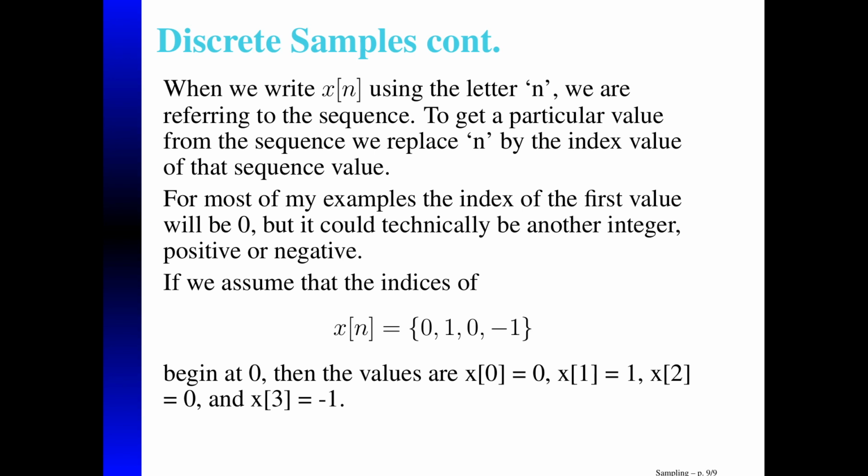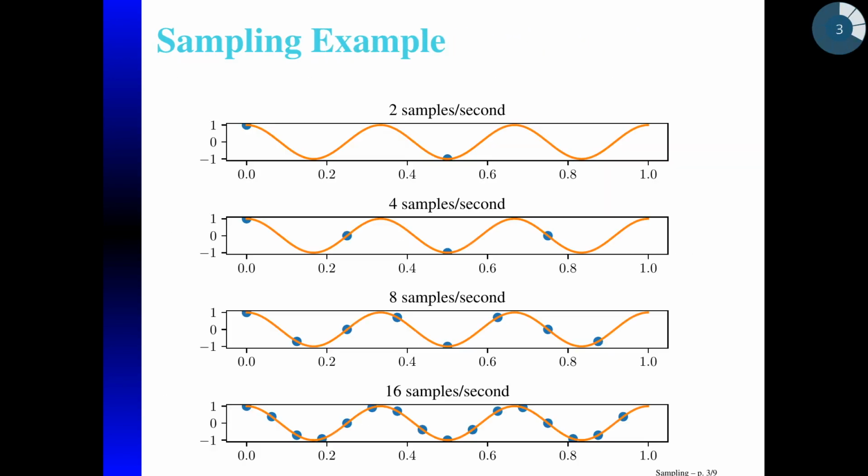What we'll discuss in another video is aliasing, and we also will discuss how many samples to produce, because going back to this example here, we said that we can easily see that 2 samples per second for a 3 Hertz wave, or cosine wave here, is not sufficient to reconstruct the wave, and 16 is too much. We'll see there's a formula that allows us to determine the minimum number of samples needed to reconstruct a signal.